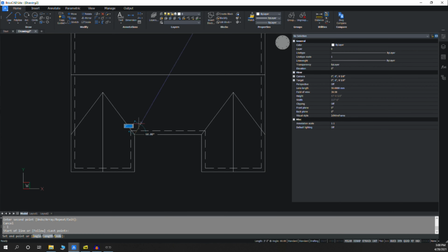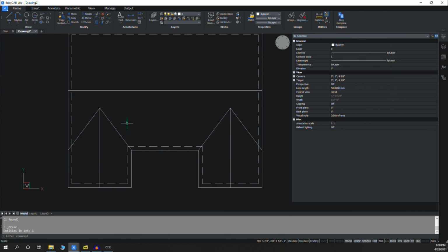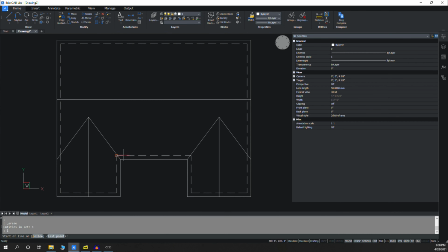If you remember how we did that, normally if we're making a roof, we'd always make a 12-foot line, and then the height would be the pitch of the roof, like say 6 foot. For these, when you have gables intersecting that are different pitches, you make one line in the direction of the first roof, and you make that line the length of whatever the pitch is.